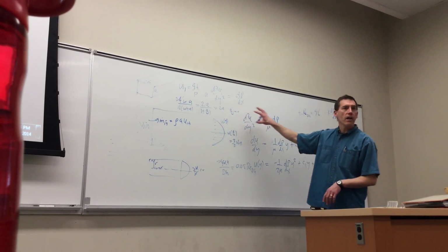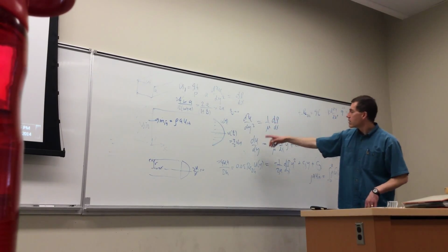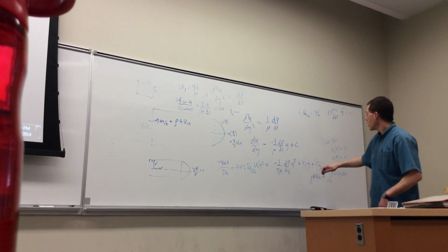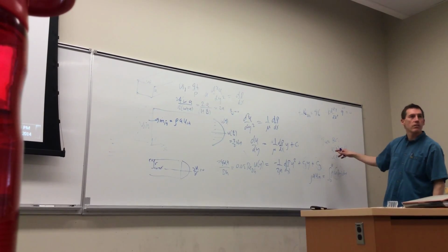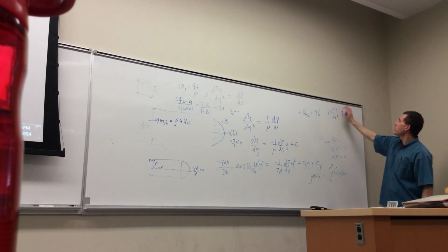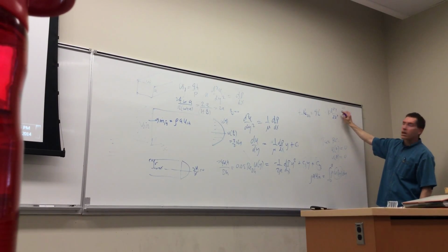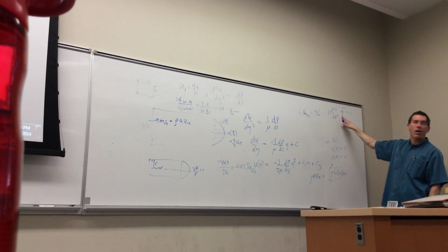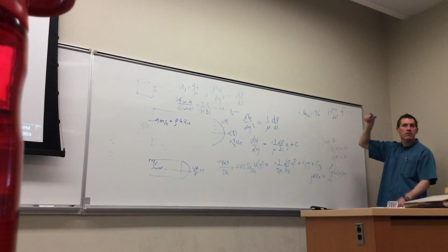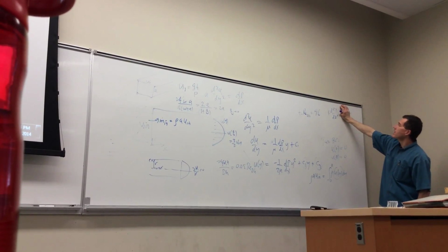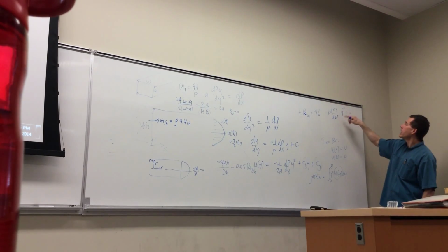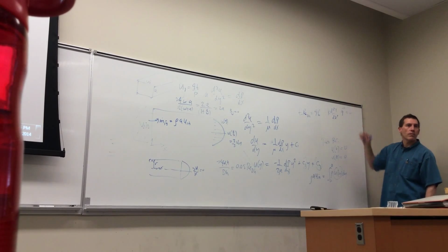So are you okay then with the solution? It's the second order differential equation, integrate twice. You get the coefficients from the boundary conditions. It's just like what we did for this, right? When we did conduction, well, the textbook does this one. If you have a source for conduction in a plane wall, this becomes a parabolic temperature profile, right? T is a function of x squared. But what we did is this case, and you integrate twice, you get a linear profile. And you can get your two coefficients from the boundary conditions.